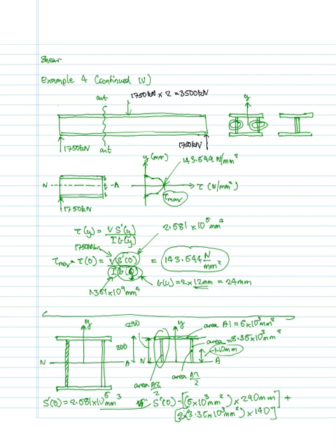But all I'm trying to say is that that stress, 143.644 newtons per millimeter squared, is applied to both webs if you wanted to turn that shear stress into a force. And remember, at the start here we had 2 times 12 millimeters for our value of B.